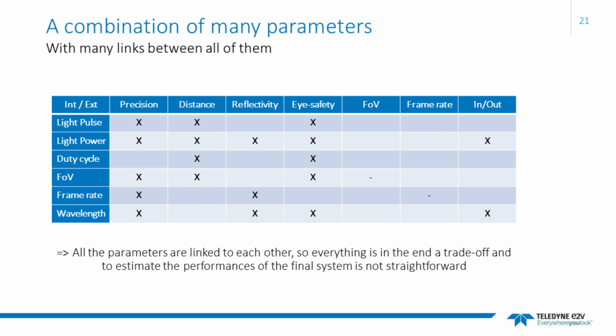We saw that pulse time of flight is useful in a large variety of cases. However, even if the sensor can be the same in all cases, a lot of things need to be adapted at system level to match with the parameters. For example, the lens to fit with the required field of view. But if the field of view is modified, it has consequences on a lot of other parameters.